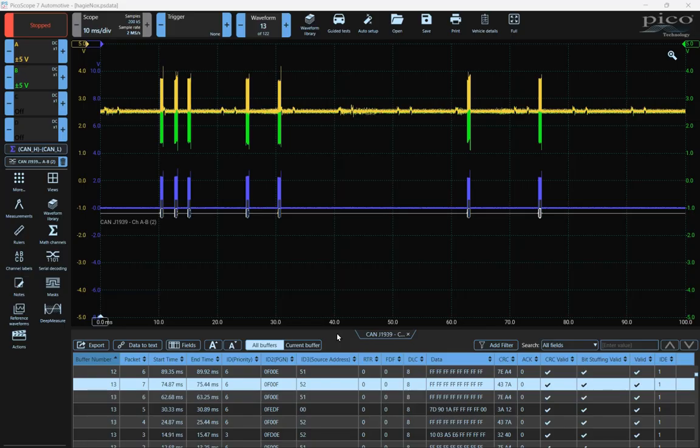So a brief loss of communication with the NOx sensors for the engine control unit, typically the rule of thumb is if I miss the message by 5 cycles. So if this message is supposed to be broadcast, we'll just say 100 milliseconds. So every tenth of a second, it's supposed to be broadcast. If that message is missing for 5 cycles or half a second, 500 milliseconds, then there may be a timeout fault that would be set for it. So something like the DEF header, you can see that it's not even transmitted once.